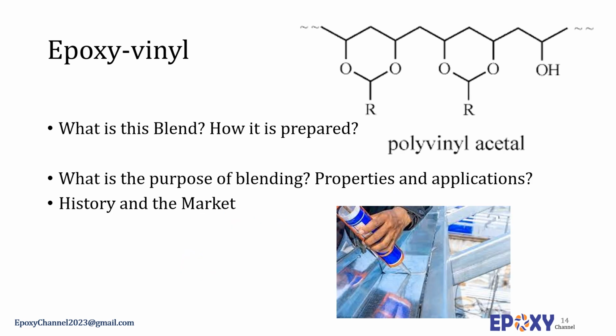Epoxy resin may be blended with certain vinyl polymers to improve the impact strain and peel strain of the adhesives. Polyvinyl acetals, such as polyvinyl butyral and polyvinyl formal, and polyvinyl esters are compatible with diglycidyl ether of bisphenol A epoxy resins when added at concentrations of 10 to 20% by weight. Vinyl epoxy adhesives have moderate strength at temperatures up to 150 centigrade.